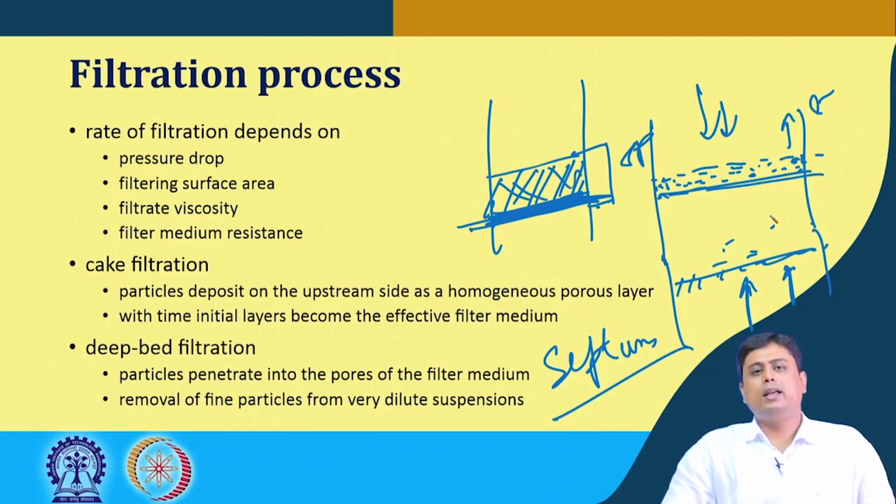Now, you can understand that if the bed, cake, or filter media is of small particles or packed orientation, then this back washing followed by fluidization can help in recovering the bed. So, the point is that in these cases, post filtration, this back washing or back flushing of the bed of the filter media is typically done to recover the filter media, and then again it is reutilized.